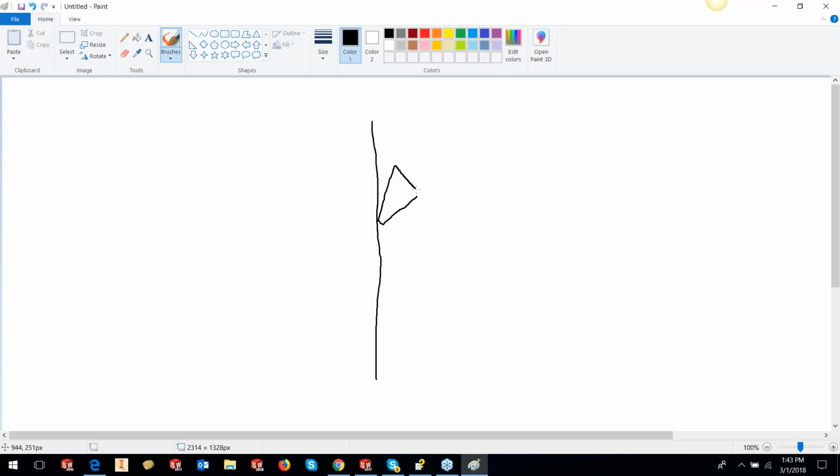Okay, something like this. Although this should have been aligned, but that's okay. The tool contact line in this case is not going to be this one, but the tool contact line will be this line, or the taper line, with the 10-degree line, and the tool will retract itself out in that way. Okay, tool won't retract in this way, but tool will retract along the tool contact line.